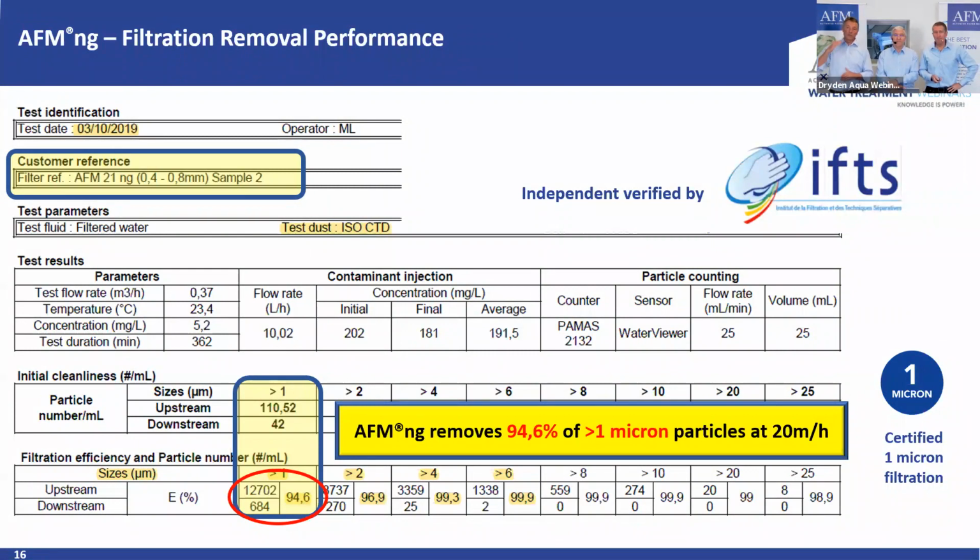Yeah, exactly. And we have taken 20. You know, water treatment usually is around 10. Swimming pools is around 30. So we took the 20 to be in the middle. You know, each of these tests cost more than 5,000 euros. So, and we tested different medias, sand, AFM, a lot of glass, all these glass, you can forget that. It's really the second best was sand.